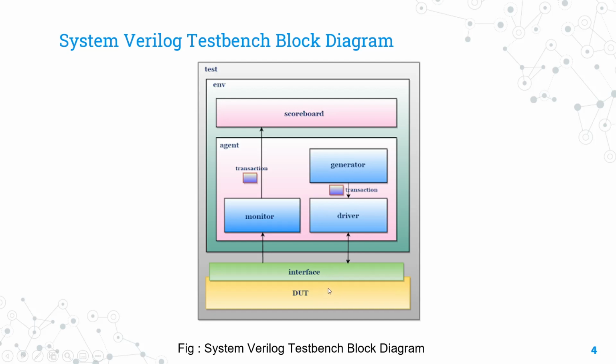The design under test will take the inputs and generate some outputs according to the input. Those will be monitored by the class called monitor. From here we will take data from the design and check whether the data is correct or wrong. From the monitor we send the data to the scoreboard, and in the scoreboard there will be a reference model. We also send data from the generator to the scoreboard, and we take the output from the monitor and send it to the scoreboard.